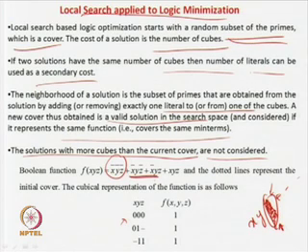Okay, and then again if you merge these two, it is nothing but y z. So, it is 1 1, and it is x and x prime. So, it is this way. So, you can represent this function in this way very easily. 0 0 0 the answer is 1, 0 1 dash the answer is 1 and 1 1 1 the answer is 1. Okay.